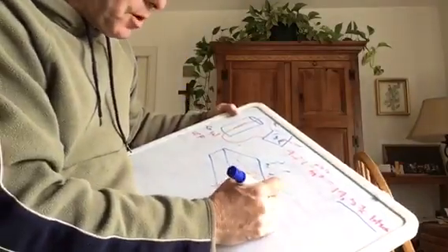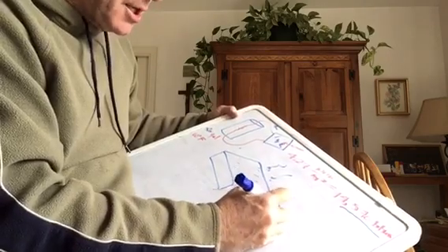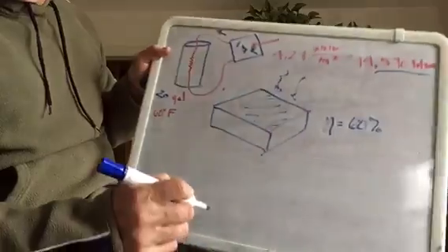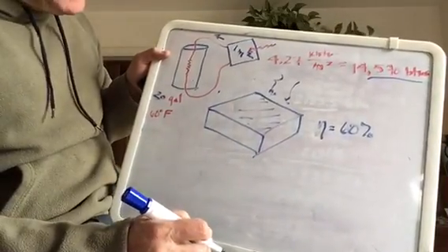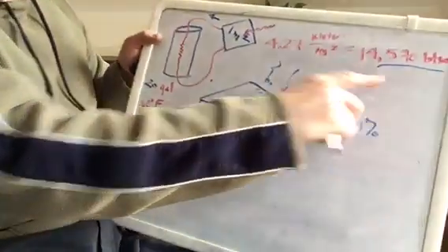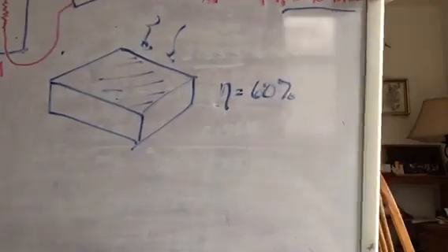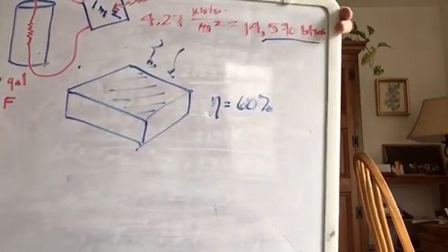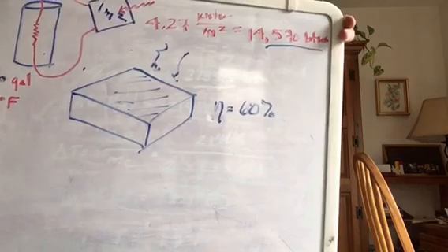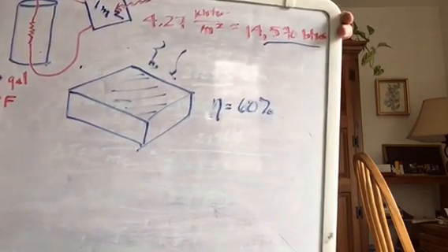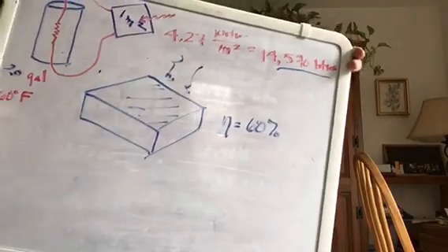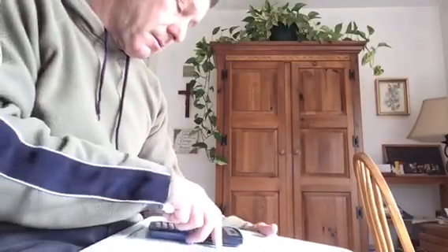but with some work, this would be a good senior project, you could get something that had a daily efficiency of 60%. So what would that mean? Of the 14,570 BTUs, 60% actually would get into the water. And then we would get the delta T. And it's going to be the same water, that same 20 gallons of water. So why don't you pull out your calculator and see if you can work through it really quickly and see what delta T you got.